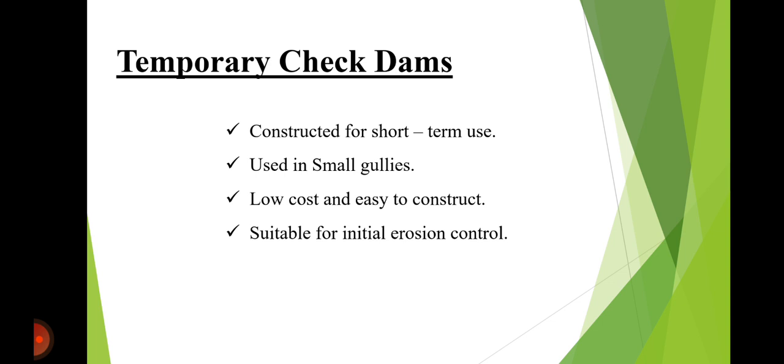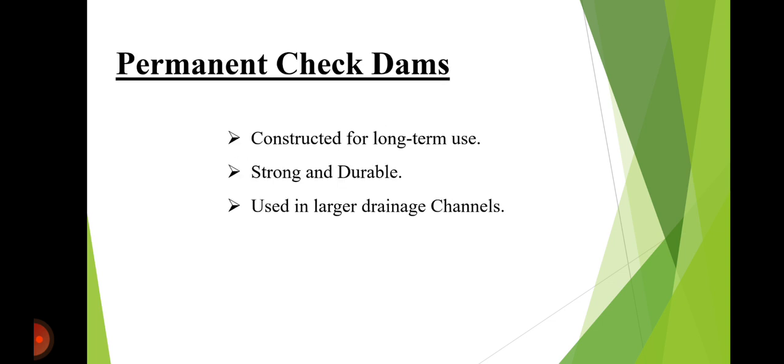The features of the temporary check dams are it is very easy and inexpensive to construct, suitable for small gullies and low to moderate runoff, have a relatively short service life, help control erosion until vegetation becomes established. Next is permanent check dams.